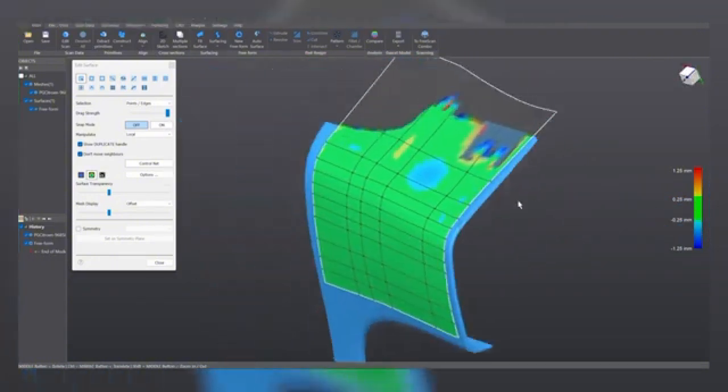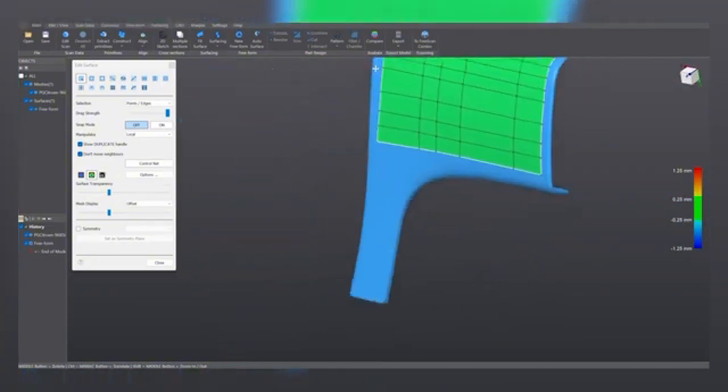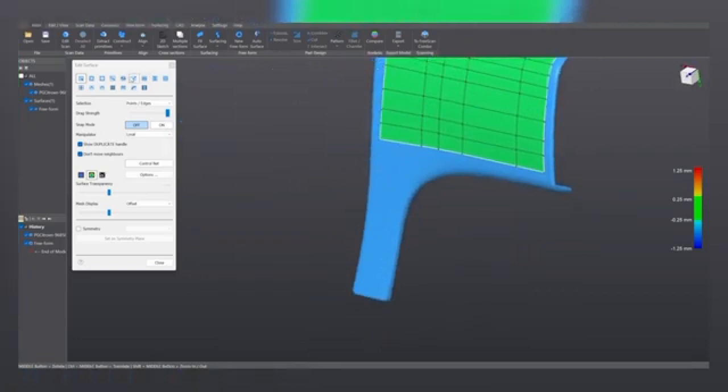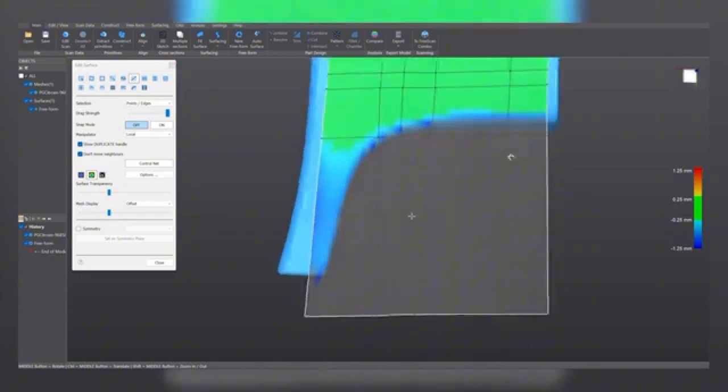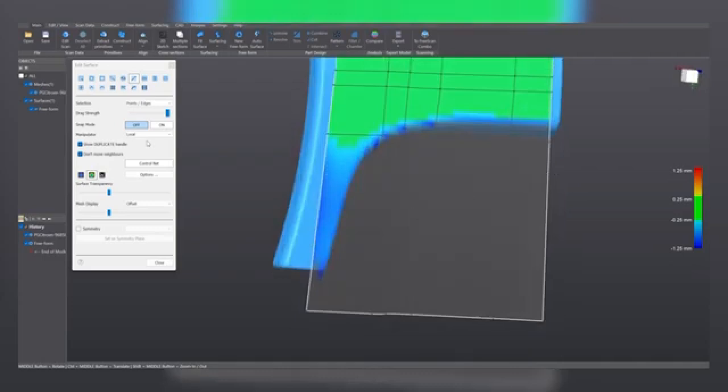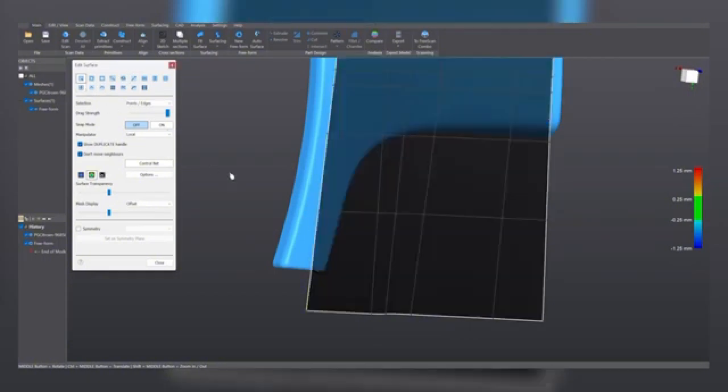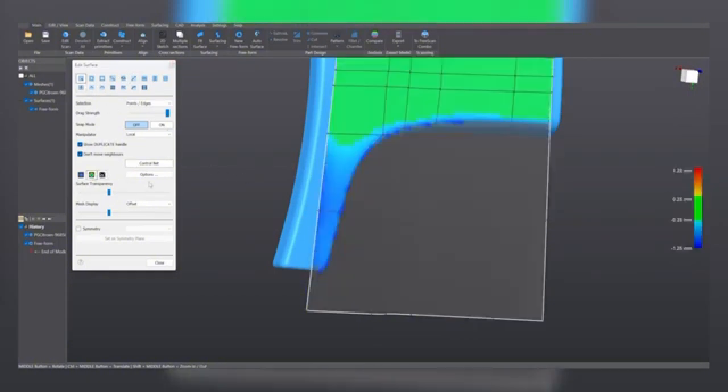Okay, and once we are satisfied with the result, let's extrapolate the surface in this opposite direction and do the same here on this side. Let's extrapolate it till here. Let's actually give it some extra resolution there. Sorry, let's select Edit, Manipulate, click on this edge and split this face. And now update the view.